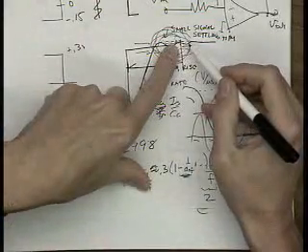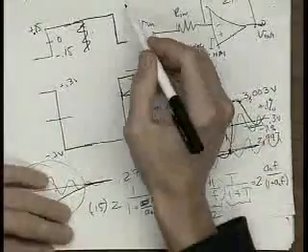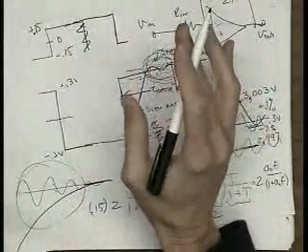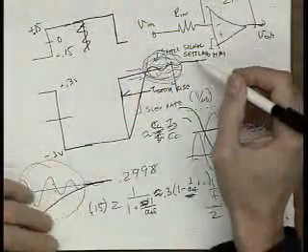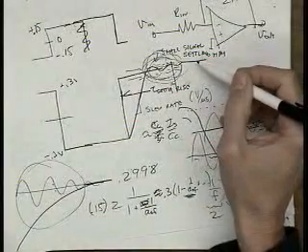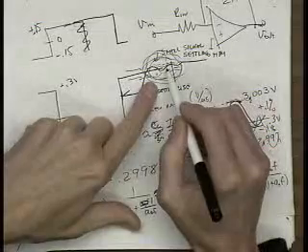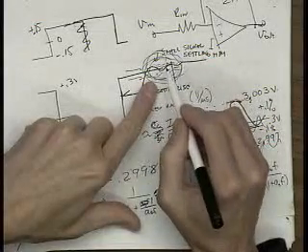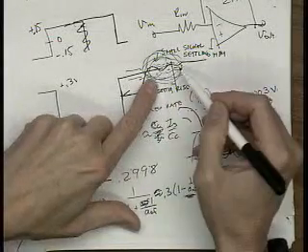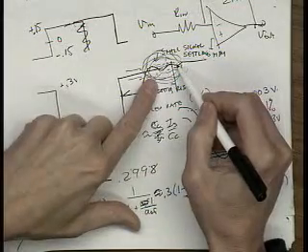This small signal settling time, you're kind of stuck a little bit by the gain bandwidth product of your amplifier. As you increase the gain, the bandwidth is going to get less. That's what this closed loop bandwidth is all about. That will slow this down. So you want to reduce the gain as much as you can in order to make the small signal settling faster.